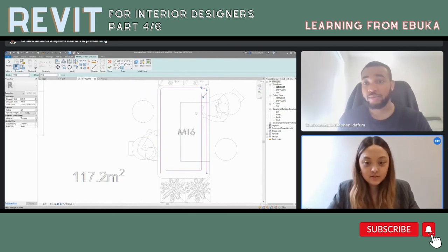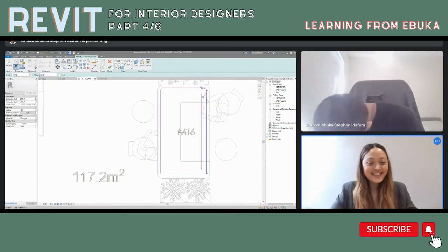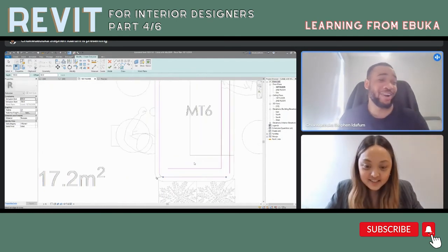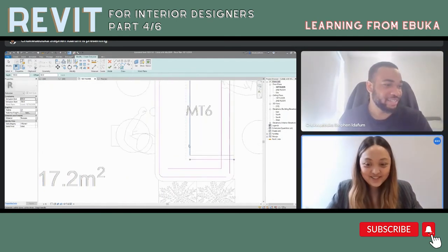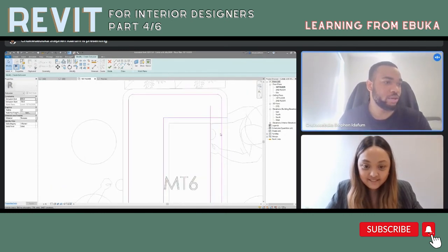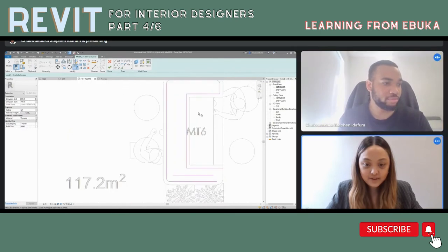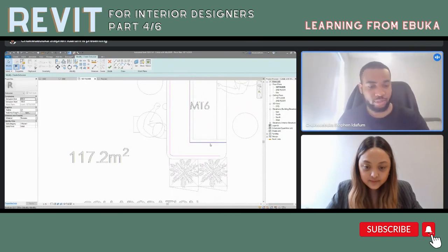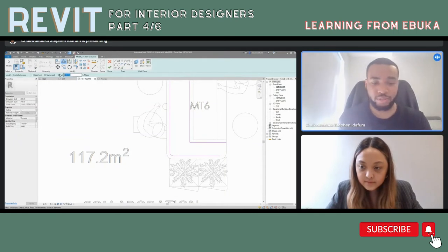Maybe not there, because we need the void as well, no? Oh, we don't even need to. Okay, so this, that, and that. Okay, we are good. So delete this part. Press TR to trim to get this part. Offsets. If I offset this part, I'll make it 50.